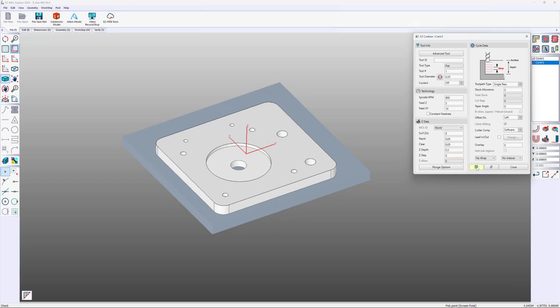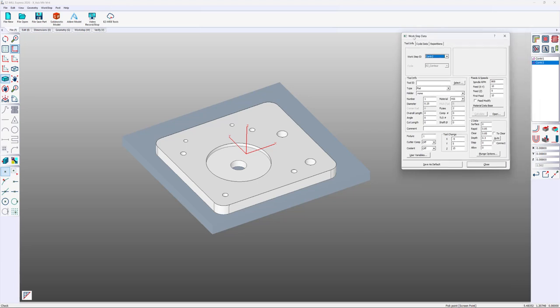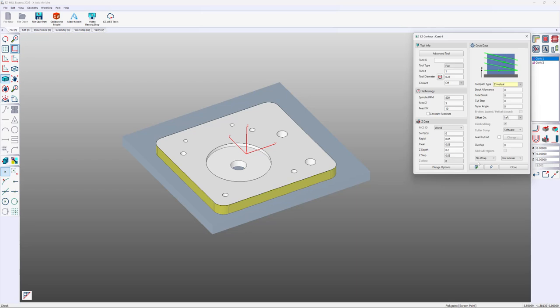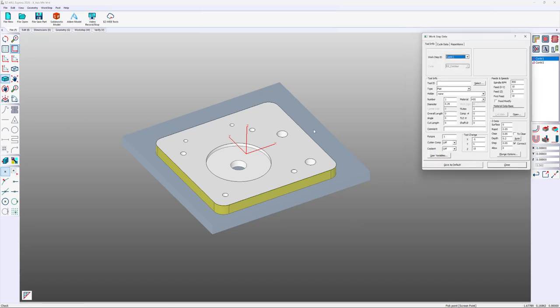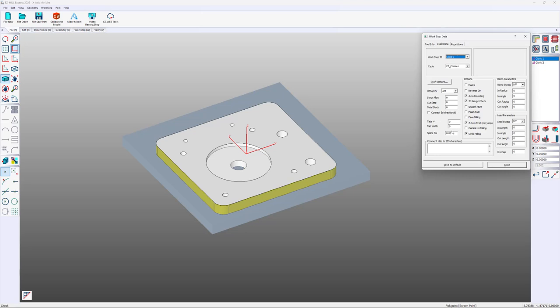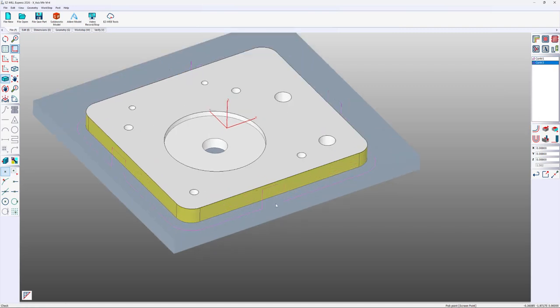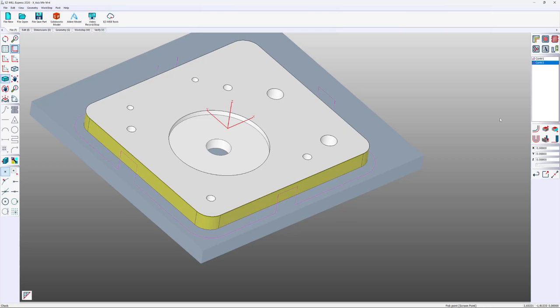Now we'll go to the background using the advanced button. Here we have more features. We'll go to cycle data. We'll make 4 tabs and we'll have a width of 125. Let's change the spline tolerance. Do the same up here for the contour. That just gives us a finer finish. Okay, there are our tabs. Let's simulate that.